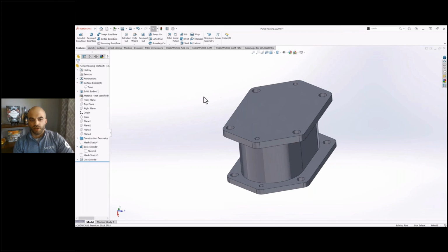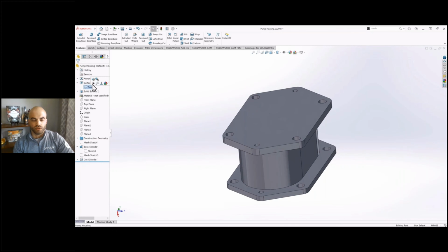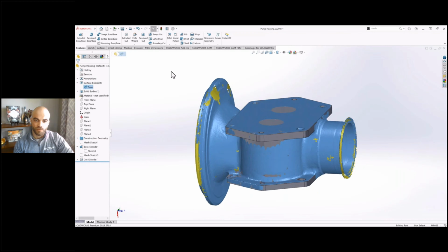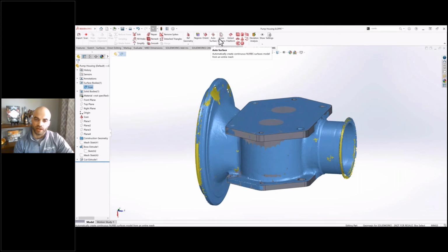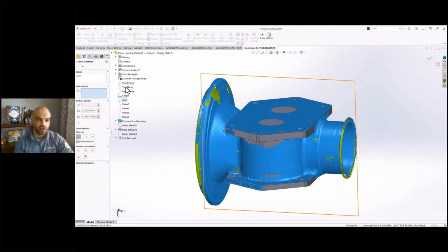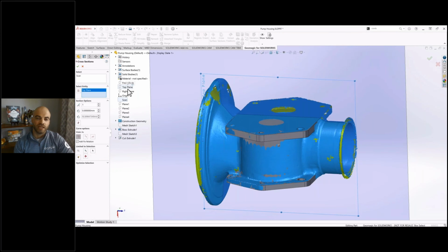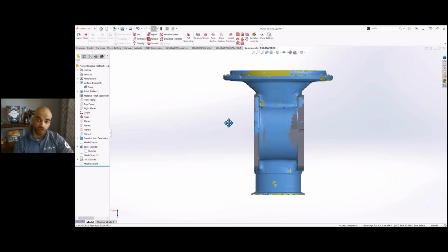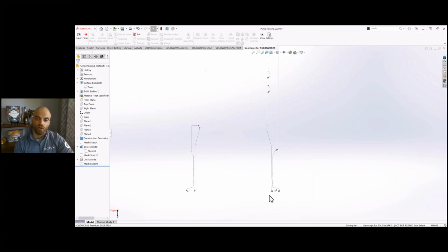So I use one of my favorite functions in SolidWorks, where you do the opposite of the profile cut, in order to get that center section cut out now. And we're looking pretty close for that middle feature, at least on the outer surfaces. We obviously have some work to do on the inner surfaces. But the main idea that I'm running with here is it should be about 3 main features, which is this center area, and then the second main feature is going to be a revolve, and we're going to follow it up with some lofting at the end here.